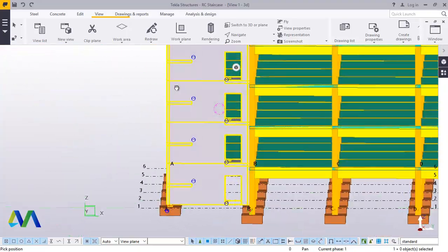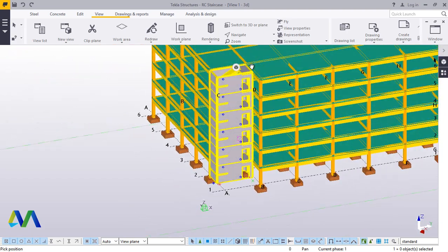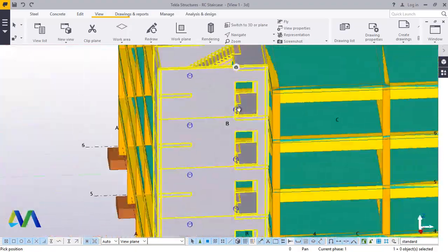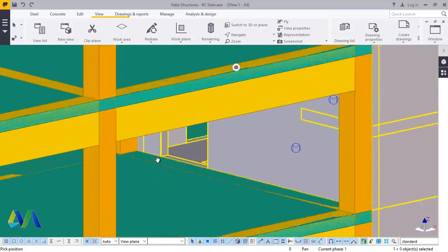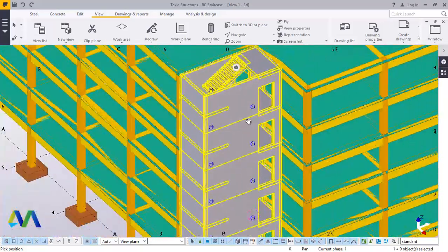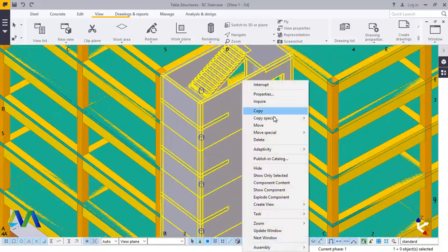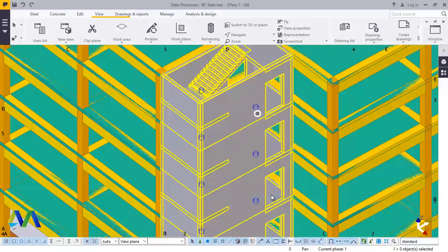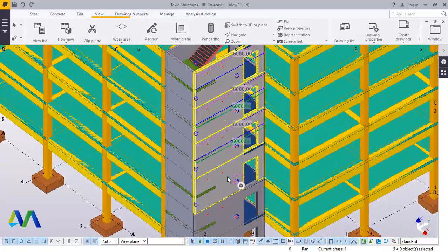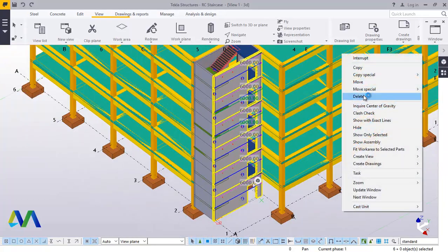We'll turn this round so we can check per floor. We have some doors there that will enable you access this floor here. Now for us, we will not be using these concrete panels. We'll click on this, right click and click explode. Once we've exploded this, we'll get rid of this concrete panel on this end, because on this end we will use glass. Right click and delete.